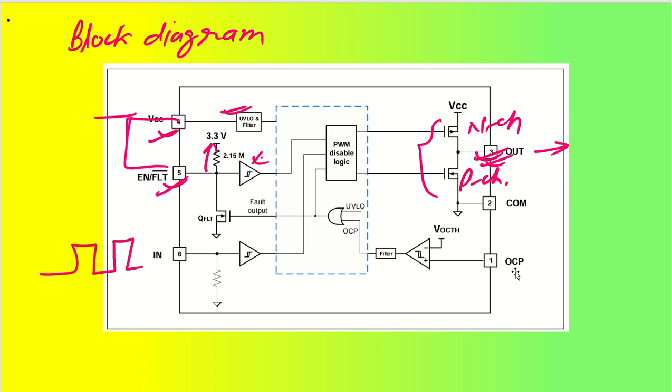And that's all. It has one overcurrent protection technique which is going to enable, checking using this particular comparator, and this comparator will be giving the fault output signal which will be taken out at the fault pin as well. So this is acting as the enable pin as well as it is going to give us the fault signal, both.